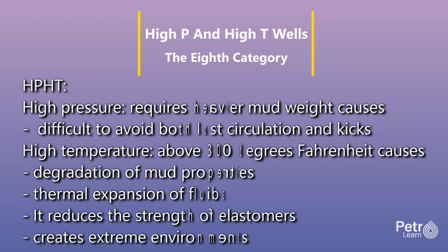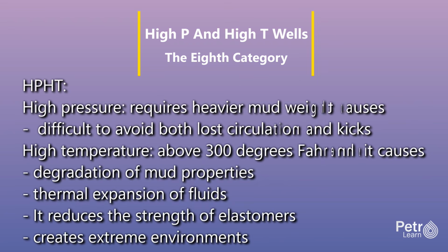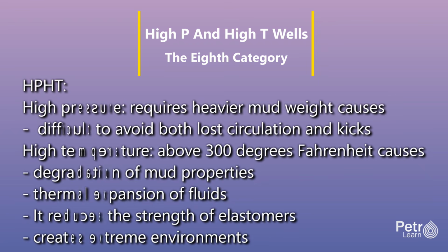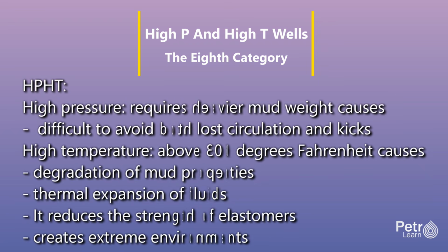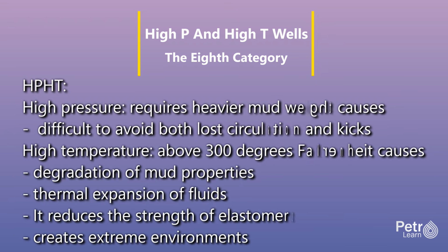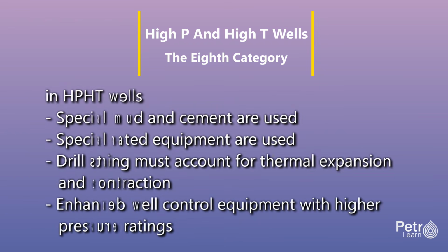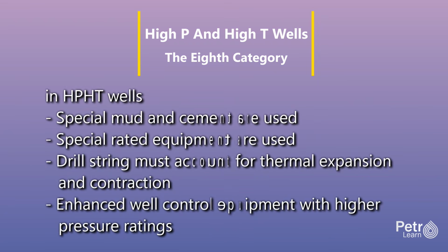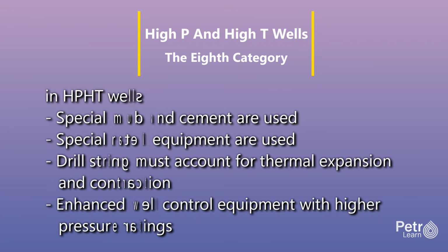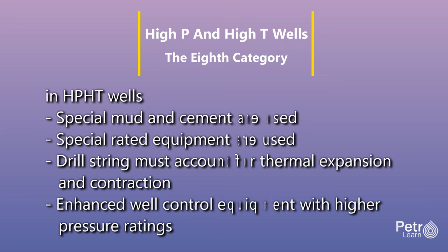High temperature, defined as bottom hole temperatures above 300 degrees Fahrenheit, has many effects, where it causes degradation of mud properties and thermal expansion of fluids, which affects pressure calculations. It reduces the strength of elastomers used in packers and BOPs and creates extreme environments for downhole electronics. Specialized muds with high temperature stabilizers, synthetic-based fluids, or even formate brines are used. Equipment is rated for the temperature environment and carefully selected. Drill string design must account for thermal expansion and contraction.